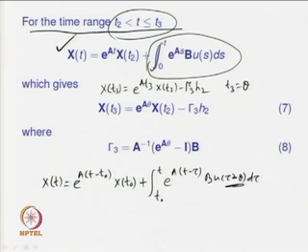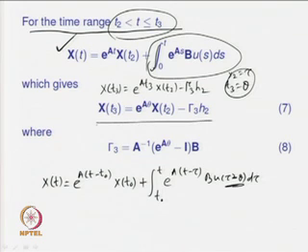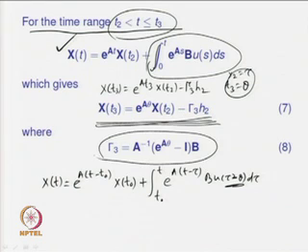As I have said, after the zero crossing x2 is equal to tau, you find the output for theta durations only, theta seconds only. So that is why the solution of the state equation can be given in the form of x(t3) is equal to e^(A theta) x(t2) minus gamma 3 h2, where gamma 3 again is found from the integral, A inverse e to the power A theta minus I, B. This integral is not difficult to find, because already I have shown you how to find the gammas from these integrals.